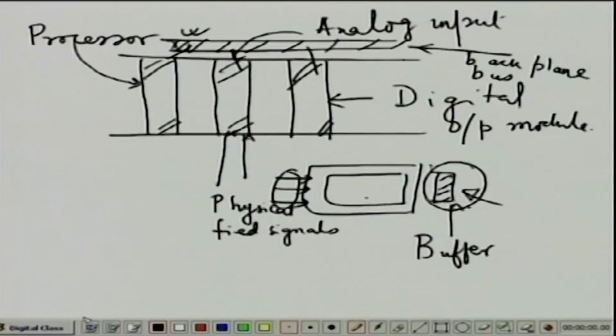So what I am trying to stress is that here there are two kinds of cycles going on. One kind of cycle continuously, cyclically samples the physical inputs and transforms them to a part of the memory which we call the IO image, and the processor, when it reads, actually reads from that image, right. Now, having understood this, so what is happening is that,